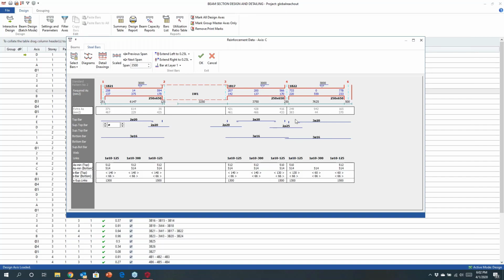Okay, so I've designed this. Now, the other interesting thing about this is that these are dynamic. So I can come in here and make changes. If I decided that I wanted to change rebar arrangements in here, I can. If I reduce it too far, you can see that we're live checking this. So instantly it's told me there that I don't have enough steel in my beam, and my steel doesn't meet the minimum code requirements, and the spacing requirements are also not satisfied.